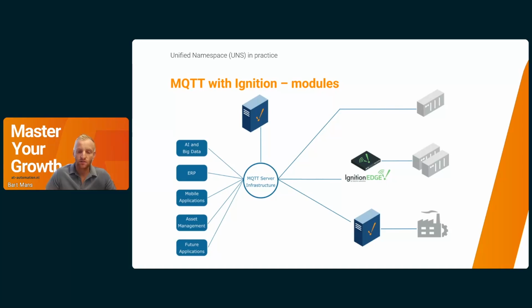If you do have a PLC or HMI or any system that is not able to communicate MQTT directly, we can, for instance, put some middleware in there. And the Ignition Edge can be the perfect middleware for that. Ignition is known for its many drivers. So we have Modbus, Profinet, Allen Bradley driver, Omron driver, Mitsubishi driver, and so on. I would need to know which B&R system you're talking to and what drivers those support, to see how we can make that connection.